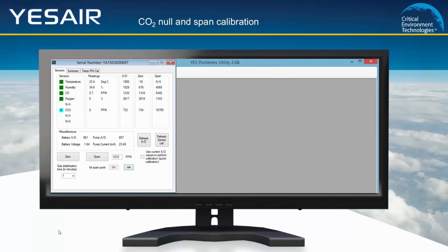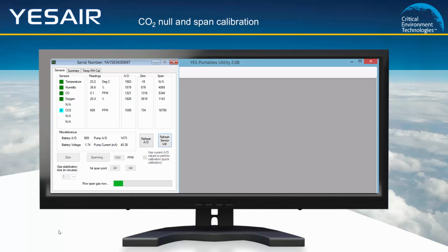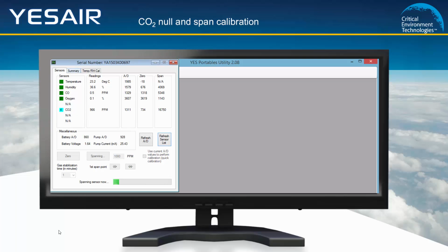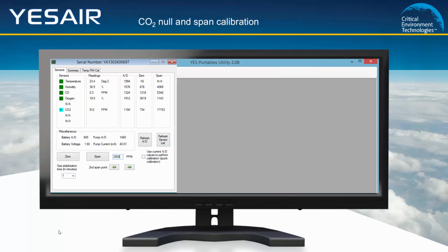Click on OK. Remove the nitrogen cylinder and attach the CO2 cylinder of 1000 ppm concentration and flow the gas. Either enter or replace whatever value is in the ppm field with 1000 and click on span. After a minute, the message, "The first span value was updated successfully," will appear. Click on OK. Change the CO2 cylinder to the 2000 ppm concentration and flow the gas.